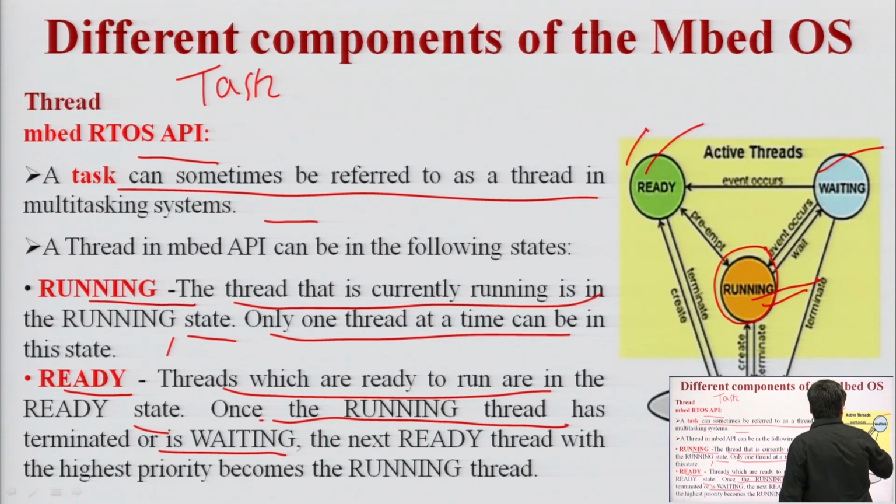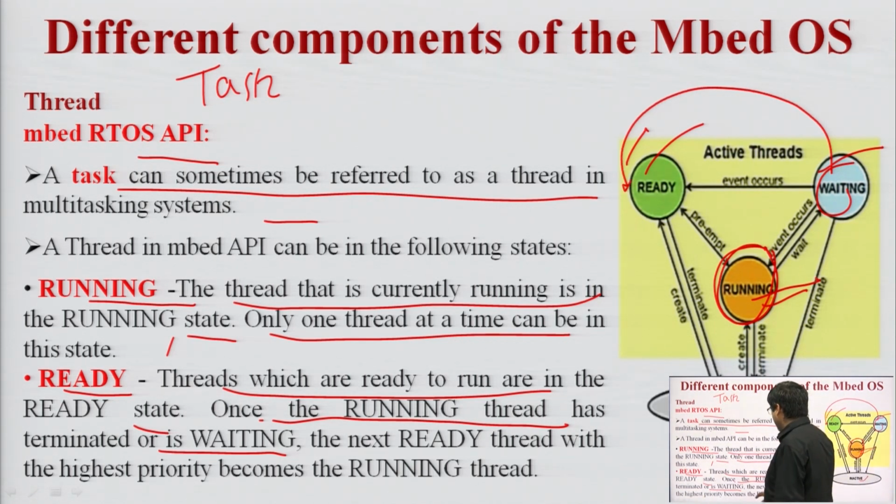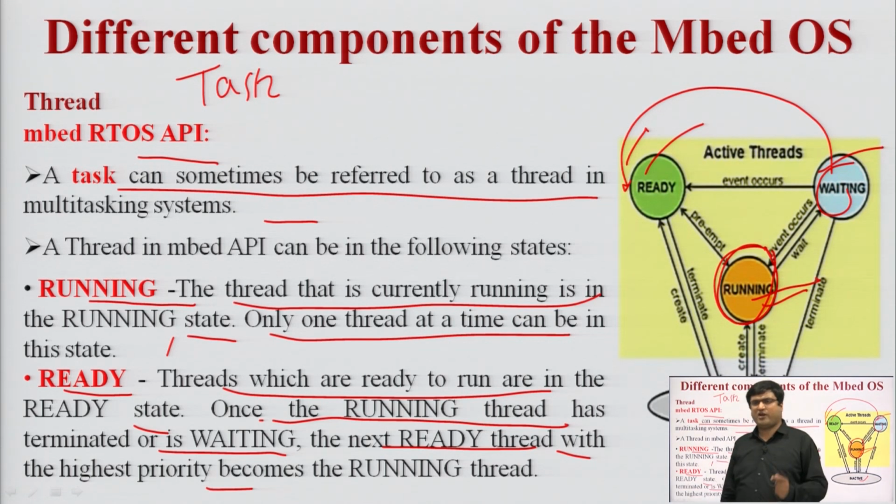Okay. So, if we are terminated this running state, waiting state, then it goes to the ready state, that is ready to run the application. Also, it has some priorities. For example, if more than one task occurs, the system will do the tasks according to the priorities of the threads. It is like interrupts, as we already said.